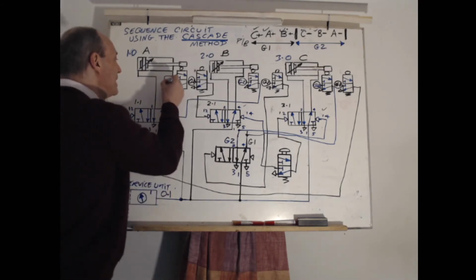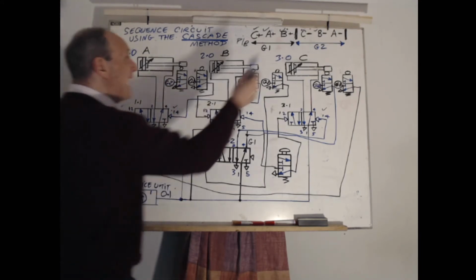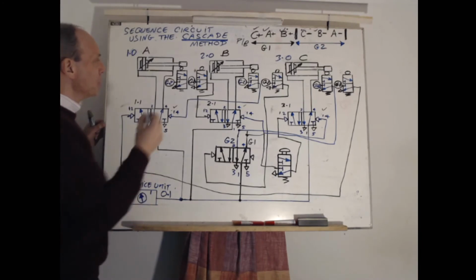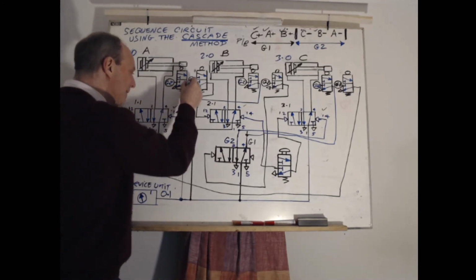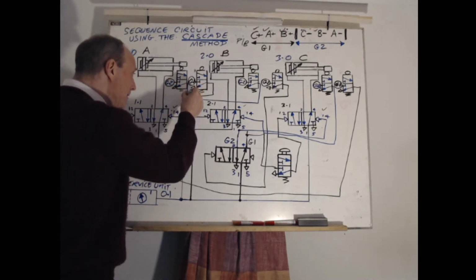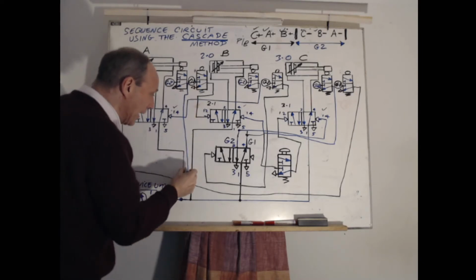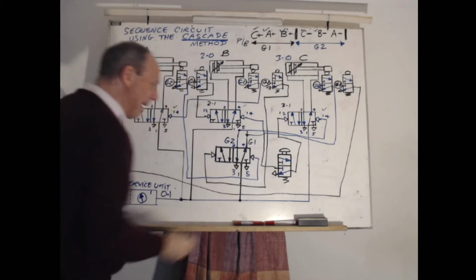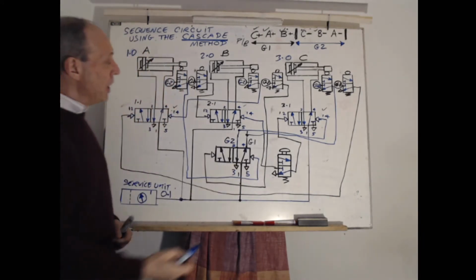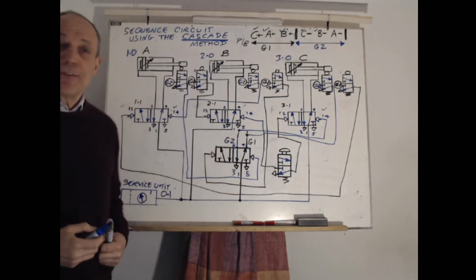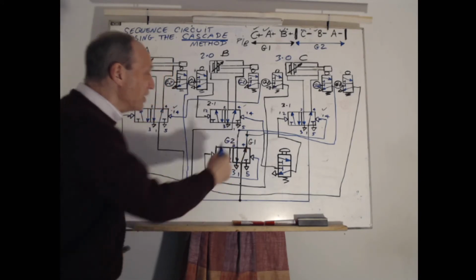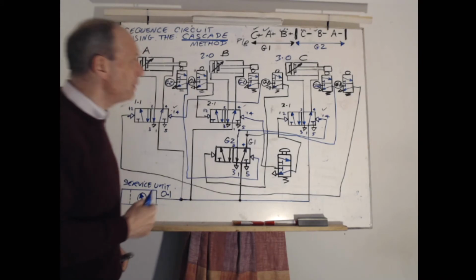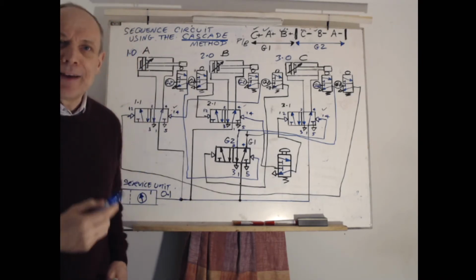This must be on G2 air. But it has the trap signal to eliminate. It wants to return to the push button stage. So the G2 air, which comes from this valve, is going to be the one that re-establishes that position on the Cascade valve to send G2 to atmosphere and bring on G1, and G1, its first stage now, is to power the push button to continue with the sequence if necessary.